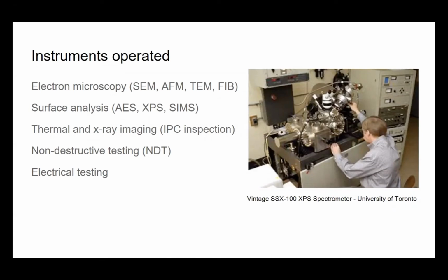Surface analysis, this is an image on the right-hand side of an SSX 100 that I actually operated way back in the 80s. And Auger electron spectroscopy, surface analysis with X-ray photoelectron spectroscopy, and SIMS. A little more challenging in terms of the spectral interpretation, but we train many technicians to operate these instruments. Thermal and X-ray imaging, non-destructive testing, and as mentioned before, electrical testing for diagnostics and failure analysis.